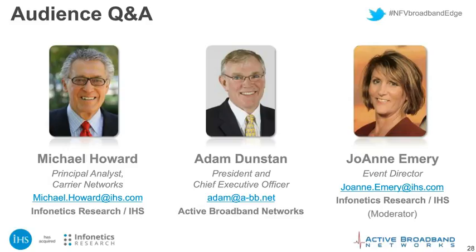When you really look at performance, one of the things about doing this in software that makes it fundamentally different is that when you build queuing systems in ASICs, you've got to think about the functionality and the scale at the same time, because once you've laid down a chip and put memory cells in it, that's what you've got. You don't get the ability to change that later. You're in the world of building parts.